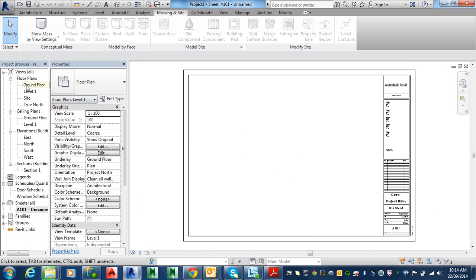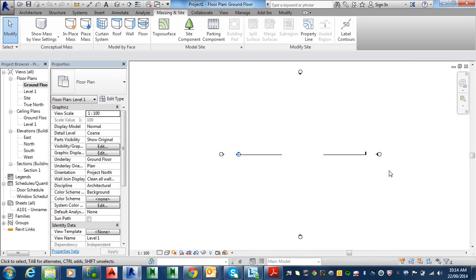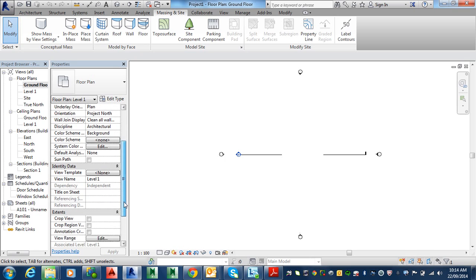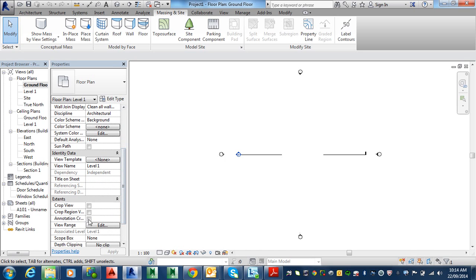All right, so we've got nothing to show at this point. The viewport has some extents already drawn, but you can't see it because it's turned off. They've turned off the viewport layer, if you want to put it that way, like you do in CAD. This is how you turn it on, by coming down here under the extents and ticking all three of these on. Once you do the second one, the top one comes. Now, I still can't see it.